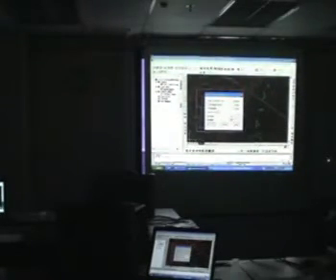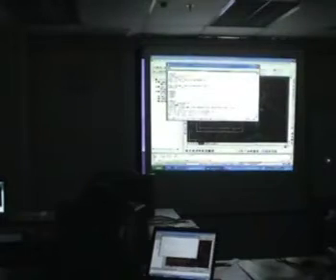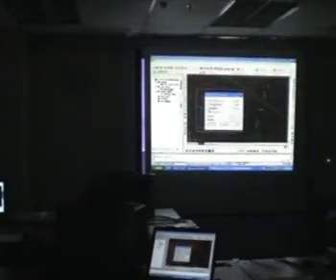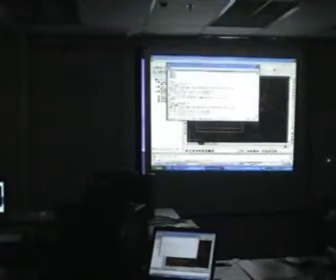I'm going to set the fill factor at 1.2, and we're going to run the average end area method first. So I'll click OK. Here you can see at the bottom, this is the volume calculation: cut, fill, and net volume. We're going to run this one more time, now using the prismoidal method. It's out. So this is the cut volume, fill volume, and our net volume.